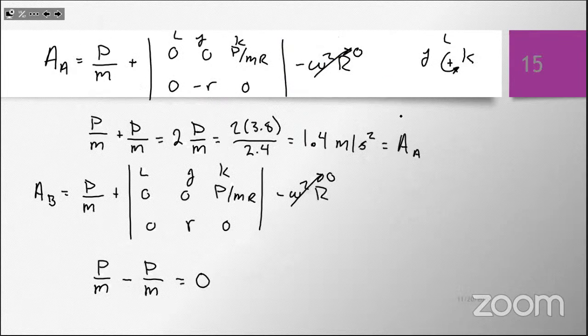So we take those equations, right? I'm going to start with A. Well, a sub x was P over M. We found that. I can take the cross product of alpha cross R, right? Alpha is in the K direction. So we've got P over M R times R in the J direction is negative R, right? Because to go from the center of gravity down to A, it was negative R on my drawing in the J direction. So, yeah, go there. Sorry, I was just looking at that.